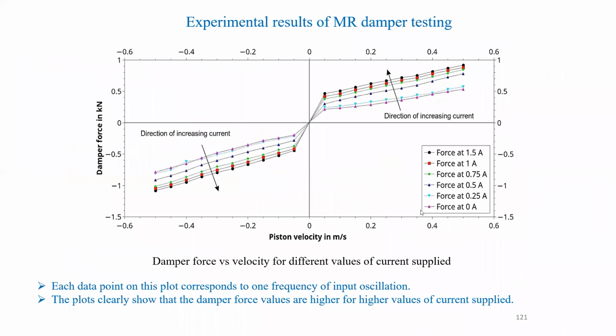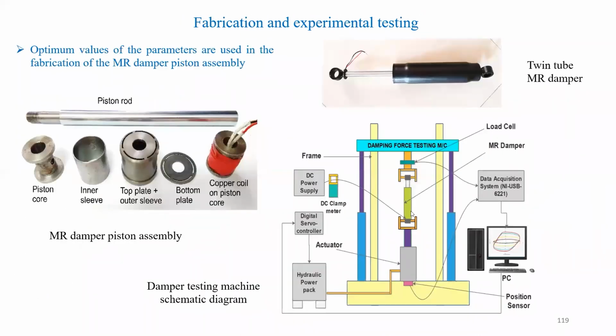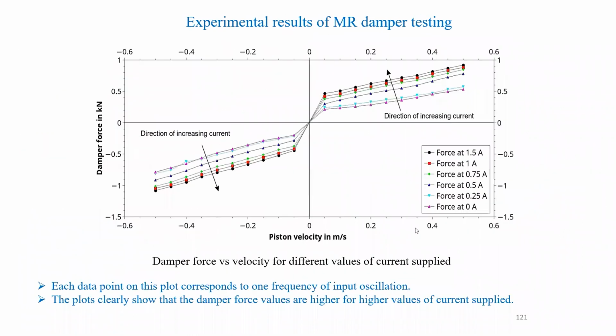actuator. If you can control the velocity of the actuator, the movement of the stroke length of the damper can also be controlled. If the stroke is controlled, then the forces are varying. The force versus displacement graph can be calculated. That is how they got that force versus displacement, and also for various velocities. Knowing this velocity and assuming there is no loss, the damping velocity versus the piston velocity can be calculated experimentally and analytically, as well as using the simulation.